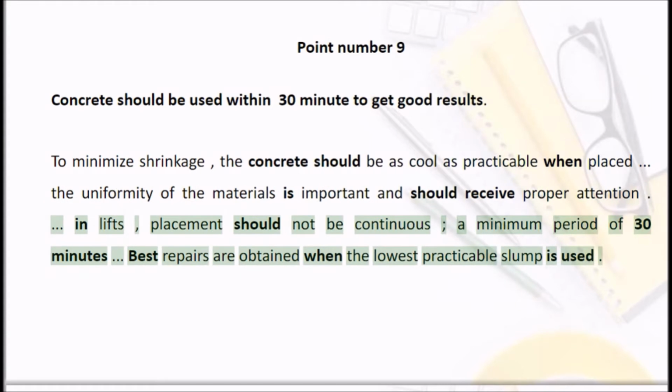In lifts, placement should not be continuous; a minimum period of 30 minutes should be allowed. Best repairs are obtained when the lowest practicable slump is used.